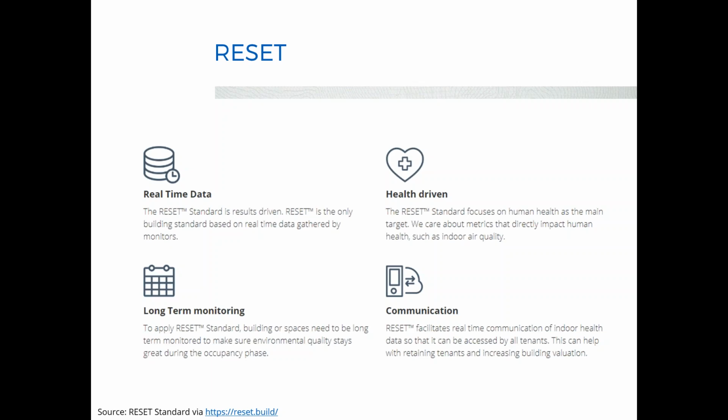So you are collecting over a period of time, but it is about a day or two that this performance testing goes on. It's not continuous monitoring, whereas RESET is about continuous monitoring of different indoor air quality contaminants over long periods of time. And so there are trade-offs between those lab-based measurement methods versus direct read measurements, due to the accuracy and resolution and the ability to detect different pollutants, like the target VOCs, for example. So right now there is a discussion going on as to what the appropriate level of accuracy and measurement approach is to really understand the indoor air pollutant concentrations and the dynamics.